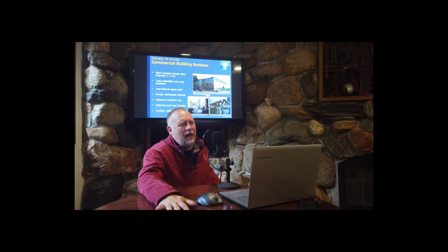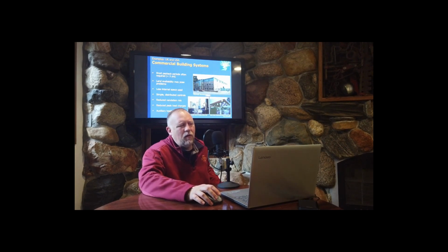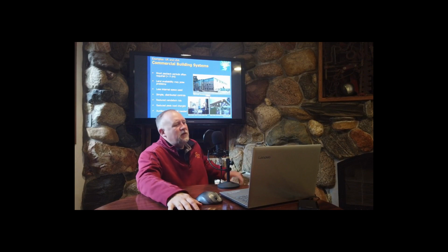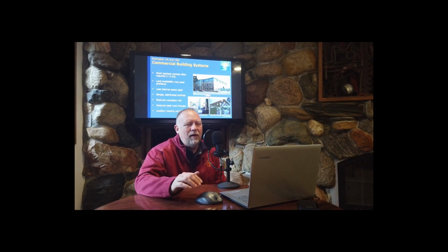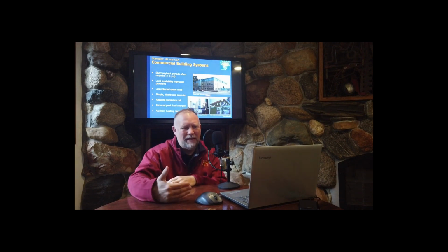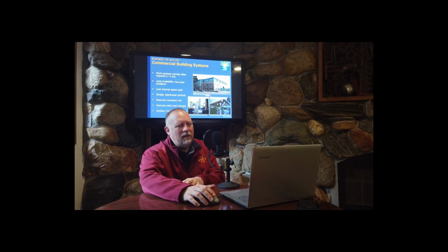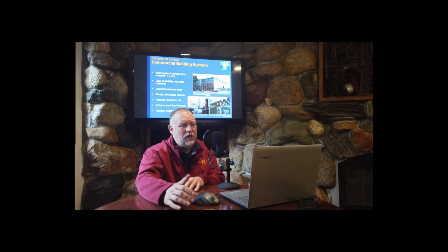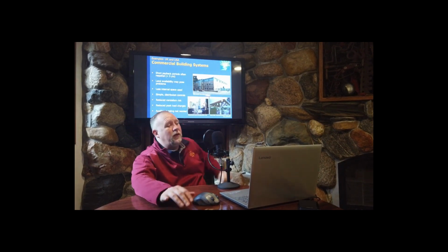This slide, and I took this slide from basically a seminar years ago on geothermal heat pump systems, talks about short payback periods. This isn't necessarily true anymore. A payback period is, well, how long is it going to take if I spend extra money today on a better system? How long would it take to pay that back? When natural gas was expensive and electricity was cheap, geothermal systems had some pretty short payback periods, but this is not true anymore.